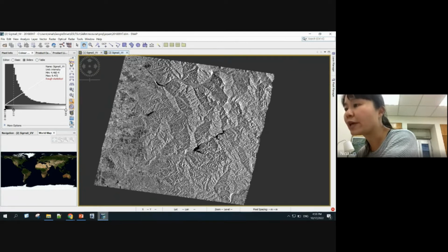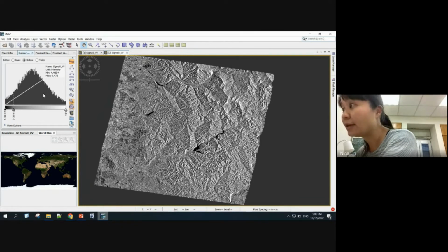You need to be very careful. I actually have this part in the PowerPoint, but I forgot to mention. So you need to come here first and click on log 10 first. Always remember the log 10 icon is not automatically turned on. You always need to turn it on manually.